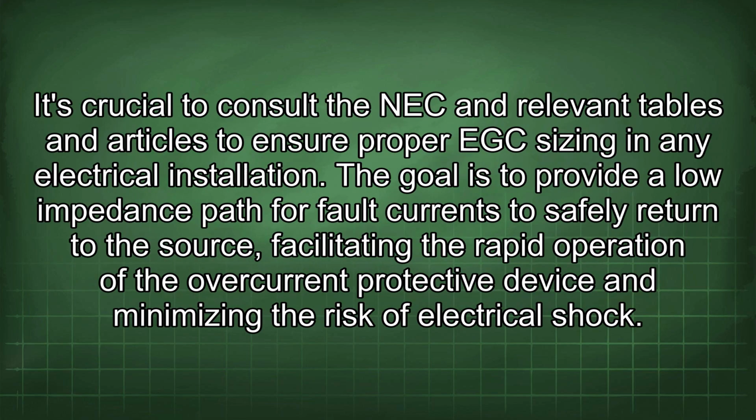It's crucial to consult the NEC in relevant tables and articles to ensure proper EGC sizing in any electrical installation. The goal is to provide a low impedance path for fault currents to safely return to the source, facilitating the rapid operation of the overcurrent protective device and minimizing the risk of electrical shock.